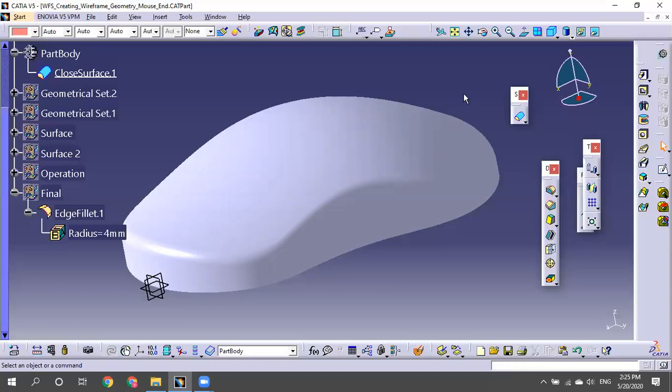Okay, to create a complex component, surface has a very good capability to bring the continuities, both in terms of tangency and curvature, where I create all my surface features, which are 0 mm thickness, that's what we call a skin, where I use all my wireframes. It could be sketches or 3D wireframes, points, lines, splines, and I organize all these wireframes and build surfaces.